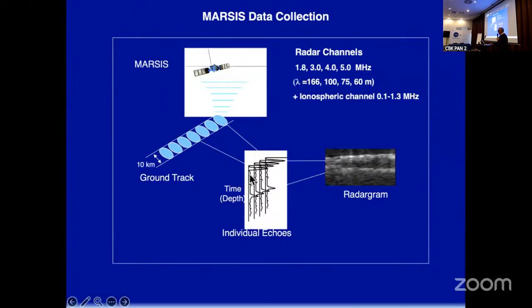We present it in the way that you have what we call fast time, with depth, which is of the order of microseconds, when the signal propagates inside and comes back. And you have the slow time here, which is the time of signal repetition, which can be milliseconds, tens of milliseconds.